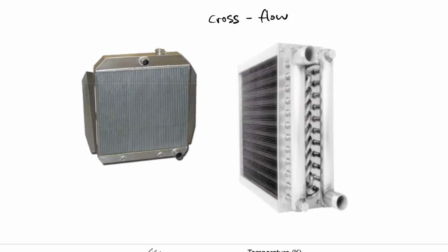Right? Crossflow is different from counterflow and parallel flow in that you have fluid that's coming in at 90 degrees from the flow path of the other channel. So the thermal behavior of these is actually a little different. It's neither parallel nor counter, but somewhere in between them in terms of its effectiveness. But here, you see that you have one fluid, usually the air, right? So the air is going to come in here.